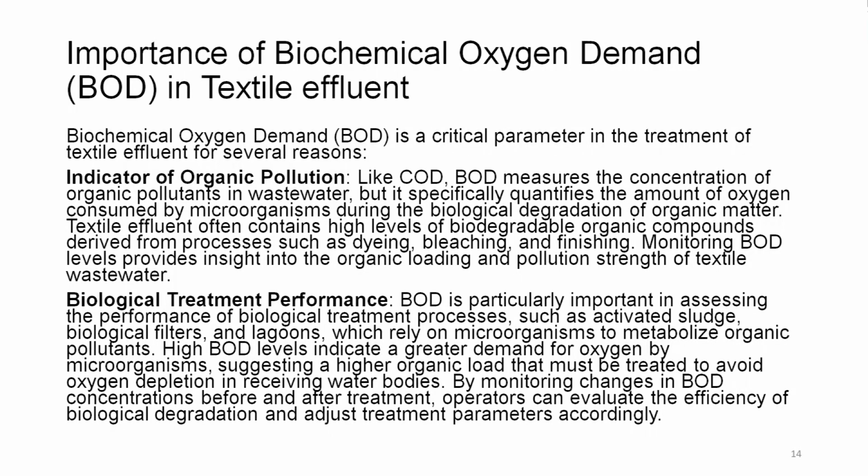Biological treatment performance. BOD is a particularly important issue in assessing the performance of biological treatment processes, such as activated sludge, biological filters and lagoons, which rely on microorganisms to metabolize organic pollutants. High BOD levels indicate a greater demand for oxygen by the microorganisms, suggesting a higher organic load that must be treated to avoid oxygen depletion in receiving water bodies.